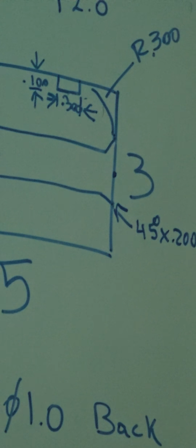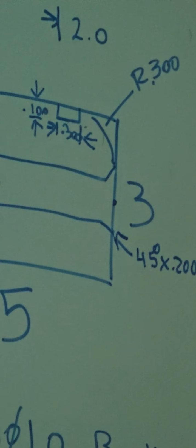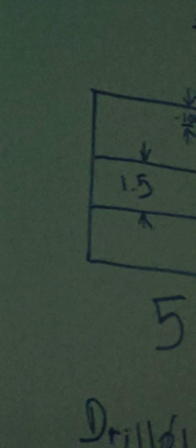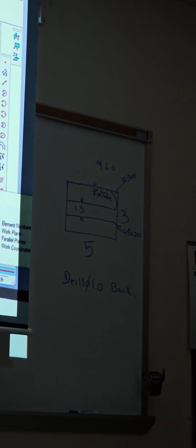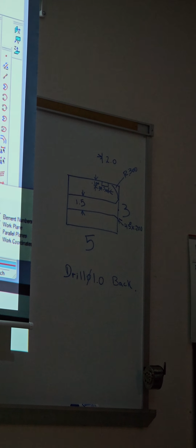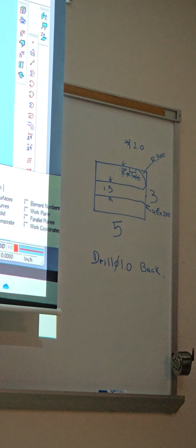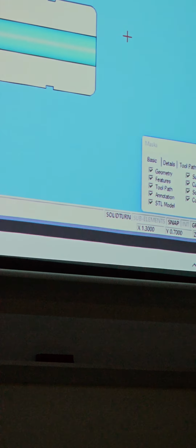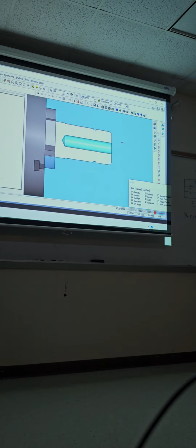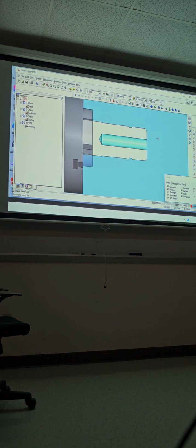And which position needs another axis of rotation. So click OK. Stop simulation. Go to tools. Down, the other one. That one. Double click on it. Go to settings. The second tab. We're about to bore. C positive. We're gonna set up for positive boring. Click OK. Try it again.